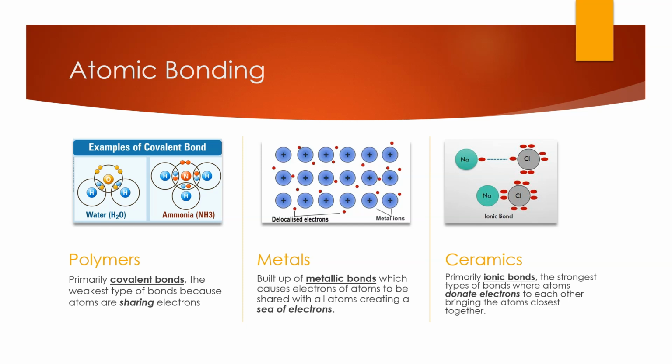Polymers are made up primarily of covalent bonds, which are the weakest type, which allows many polymers to deform and stretch with very little load. They also fracture easily due to the low bond energy. This low bond energy also causes polymers to break bond easily, which prohibits heat and electrical energy from traveling easily through them, and also makes environmental degradation a common pitfall to polymers. This is further perpetuated by microstructure, which we will see later.